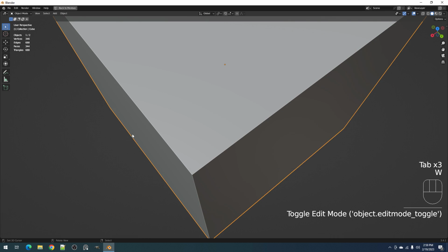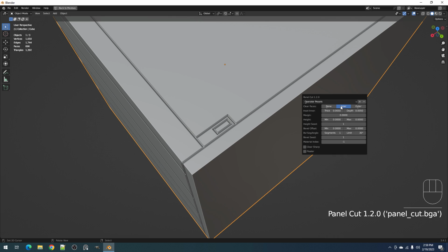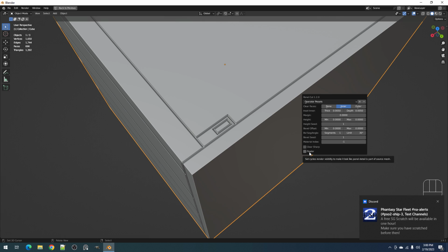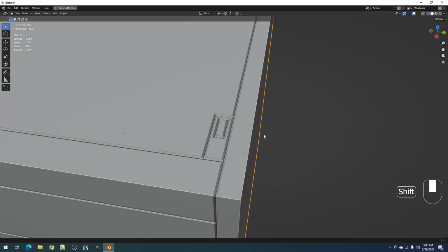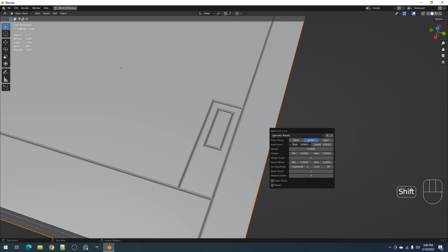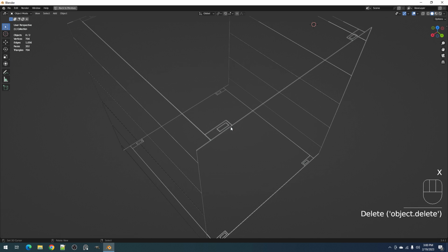Okay, now panel cut, selecting everything. And we have the inner, outer. If you press it, you get the floater toggle. So this is actually a render trick, and this will only work with Cycles. Okay, so let's edit this. Depth is a bit thinner, and this is thickness. Okay, so let's give the source object a material.